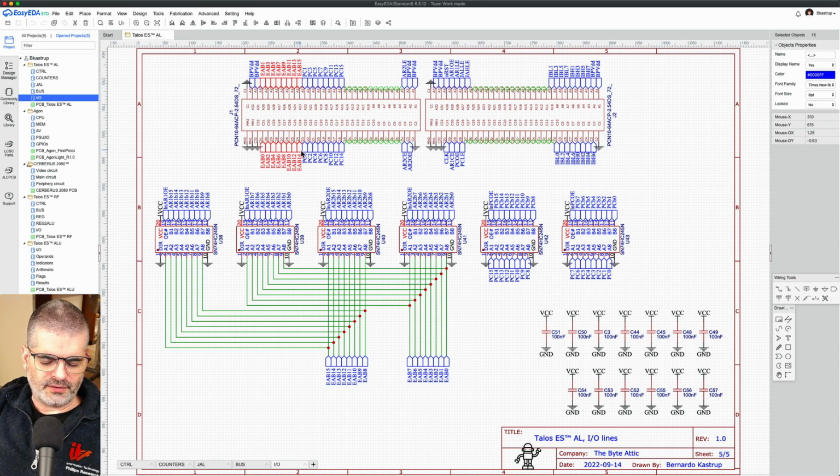A 32-bit wide direct connection between the register file card and the ALU. These are the pins that were used for that. But that's only needed between those 2 cards. So I decided I'm going to reuse those 32 lines for the external address bus and the external program counter bus to save space, but save pins. But the consequence is that the slot where you can plug the addressing logic card will now be dedicated. There will be a place where it's the only place where we can put this card. It's a trade-off. But I think it's a very reasonable one.